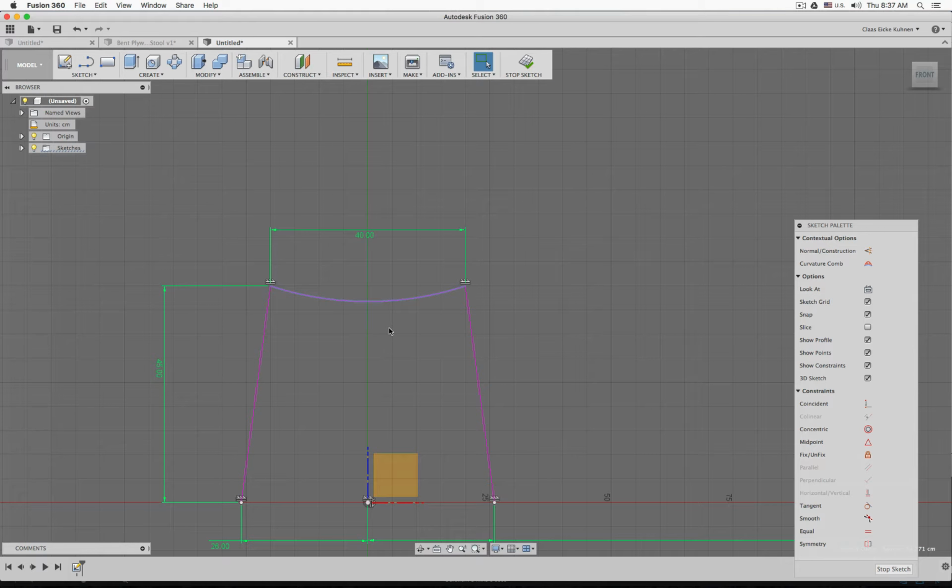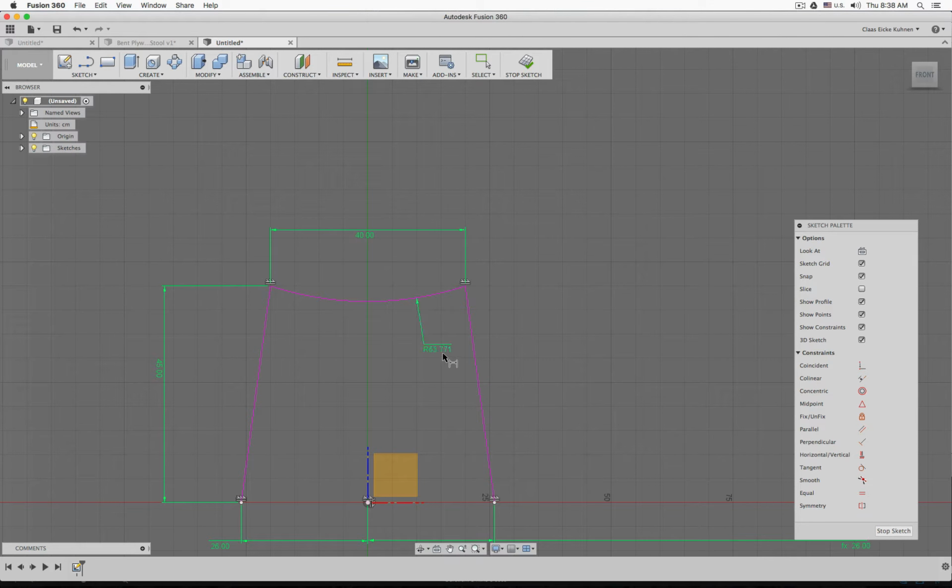That basically adjusts the radius of the arc, and you see I can actually push and pull the arc. So the arc is a perfect circle if we would close it. So we can dimension it with D and give it a radius, maybe 60 or maybe 50, 40. There you see the different changes. Whoa. Just be careful, don't give it too much. Okay. Good.